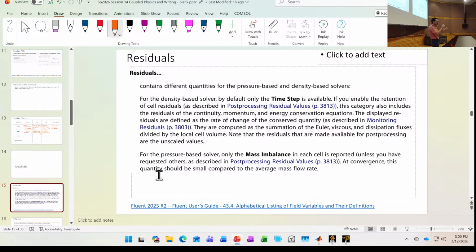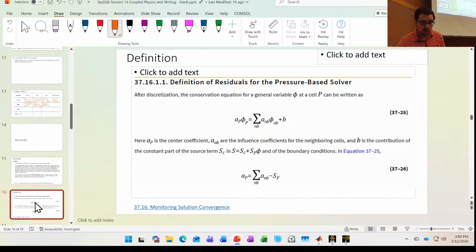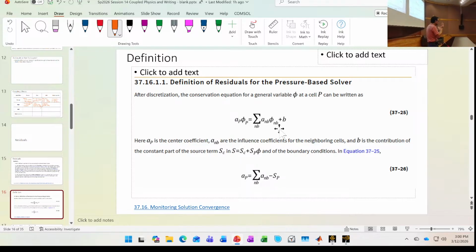that has to be going out of the system. And then if you look at the individual cells, you have to have the flow coming in and the flow coming out be close to zero in order for you to be satisfying your convergence criterion. So these are akin essentially to those Riemann sums on the surfaces and the flows that you saw.